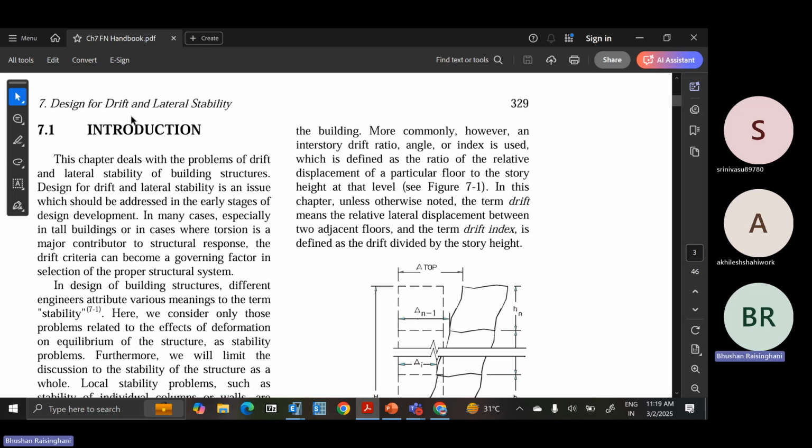So we get the PCR value, and this PCR value is a bifurcation point, because any lateral load applied after application of the critical load on the column in the axial direction will shift the column from its stable position and it will become unstable.